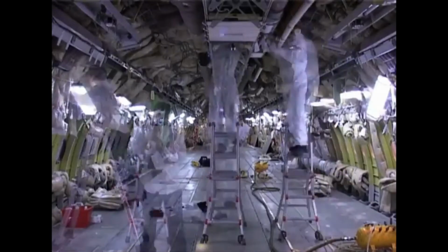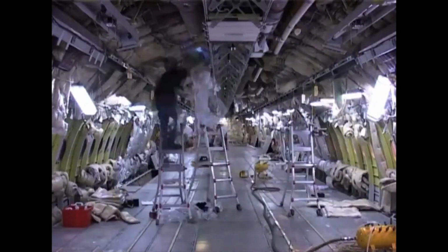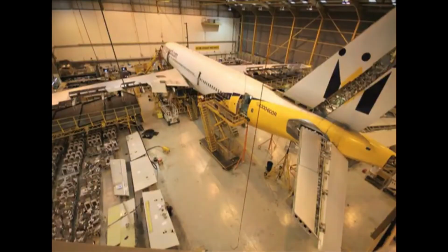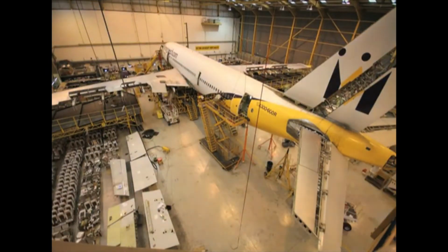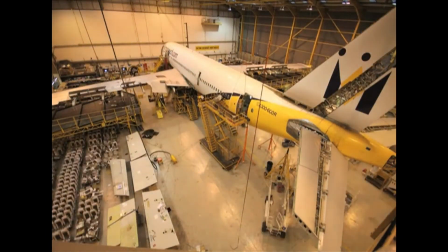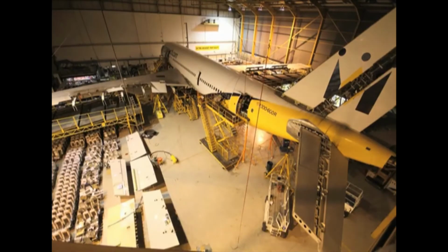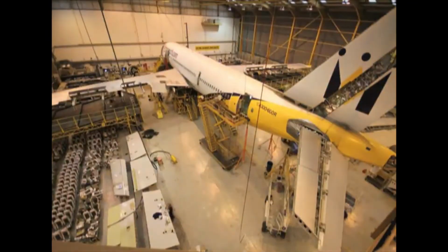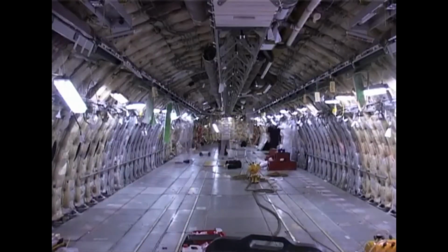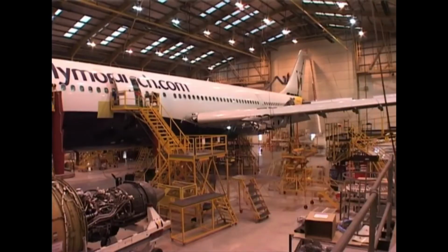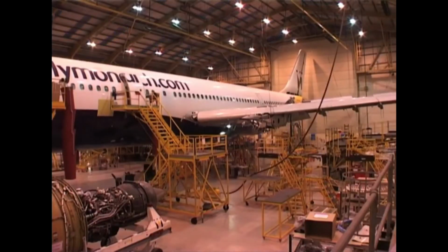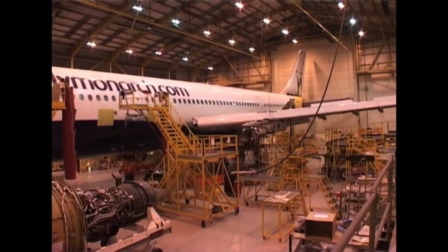When investigating damage to an aircraft, it is necessary to make an extensive inspection of the structure. When any component or group of components has been damaged, it is essential that both the damaged members and the attaching structure be investigated, since the damaging force may have been transmitted over a large area, sometimes quite remote from the point of original damage.